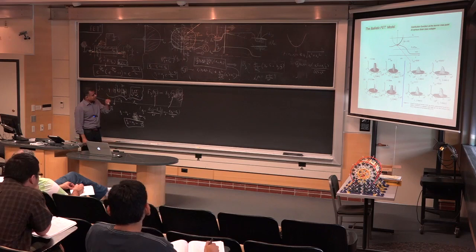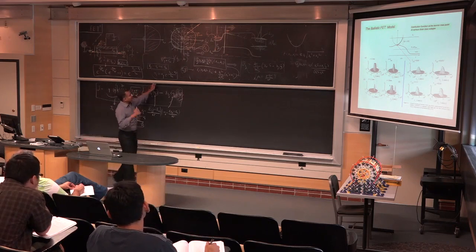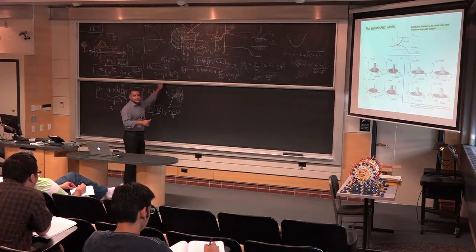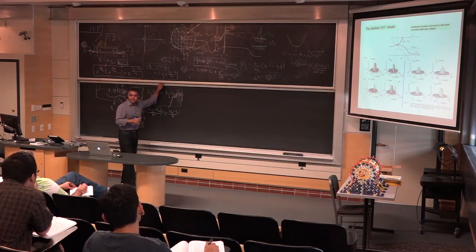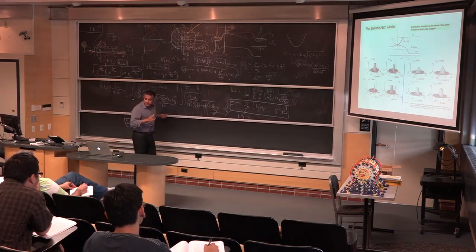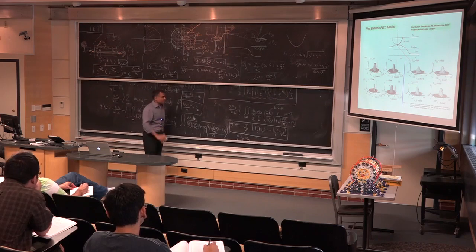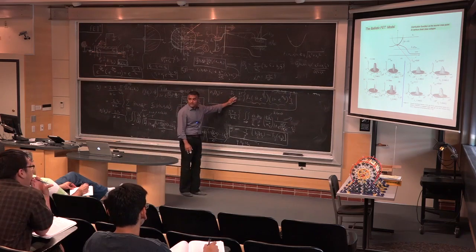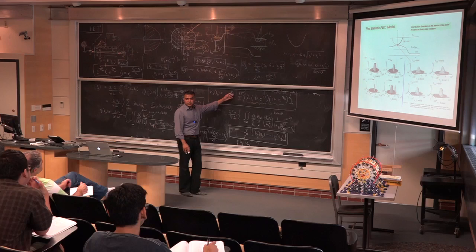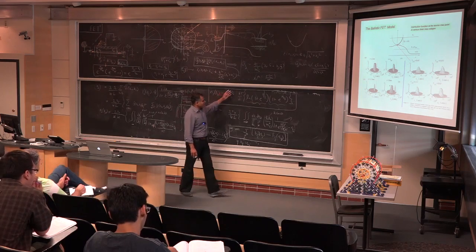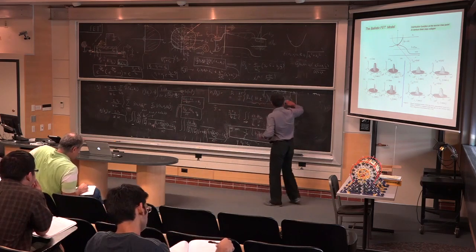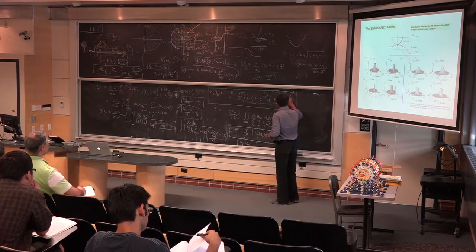Now, how do you find eta sub s? And the answer to that goes back, again, to the heart of the transistor. The heart of the transistor is the carrier density is controlled by the gate at the source injection point. And that's the heart of the problem. So you go back to here. Right? It makes sense? I mean, this is where we come back to. And realize that eta sub drain is really related to eta sub source minus VD.